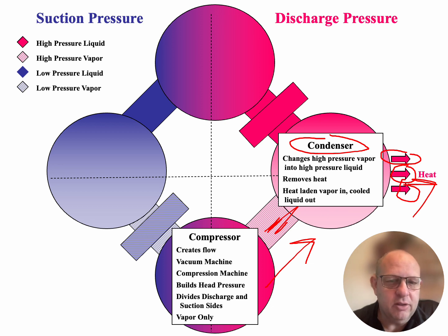much hotter than the air temperature is. Remember that heat always moves from that which is hot to that which is less hot. So we're removing heat from the condenser. Another job that we can think about the condenser doing is taking that vapor refrigerant that we have and then turning it into a liquid. And how does it do that?